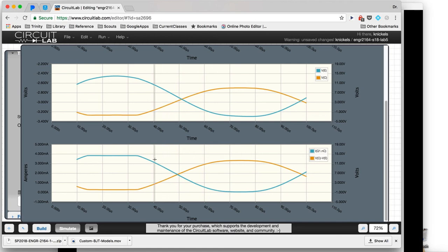But in lab, what do we do? Because we can't plot IC. We can use the math mode. We can monitor VC and VE with the scope and then use the math function to show VC minus VE. So that's not the problem. We can go ahead and generate this and check when it's flat, is VCE low? And in this case, it'll say yes. But what if it was cut off? And for different ones of your transistors, it may be cut off, it may be saturated. We don't know. So how do we check IC?